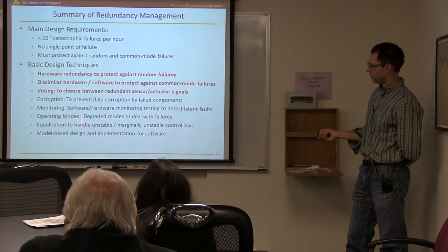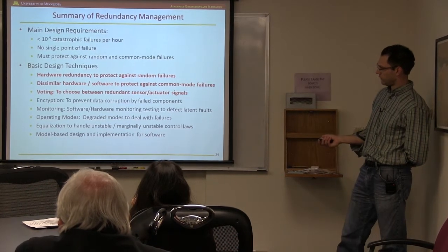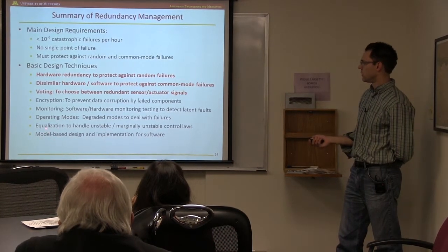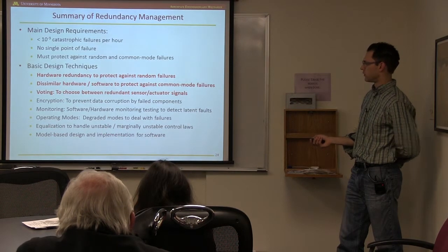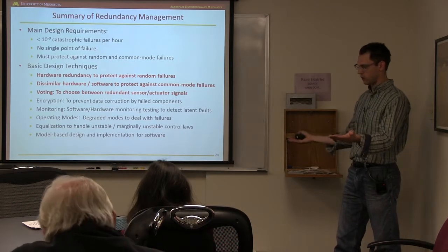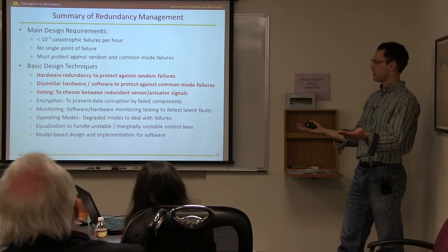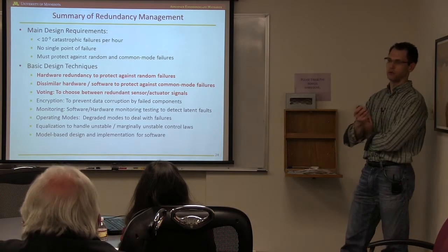And there's a whole bunch of other things that they do as well that maybe aren't so relevant in our talk. But one thing that is interesting if you're in controls is this notion of equalization. If you've got unstable control laws and you've got 3 computers, let's say one of them is flying the plane and one is just waiting on standby, that backup controller is just sitting there in open loop. It's not really flying the plane.